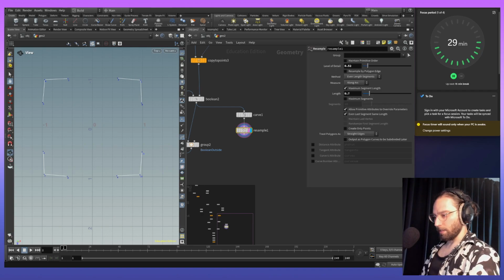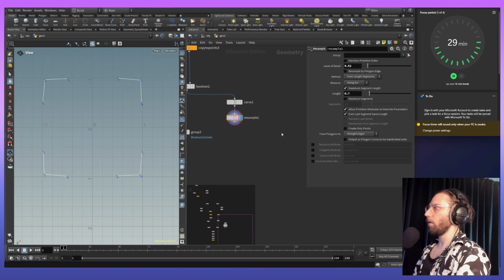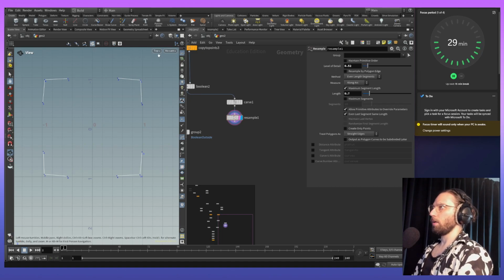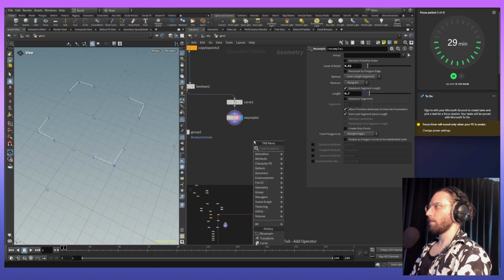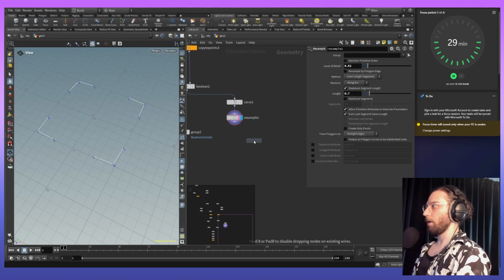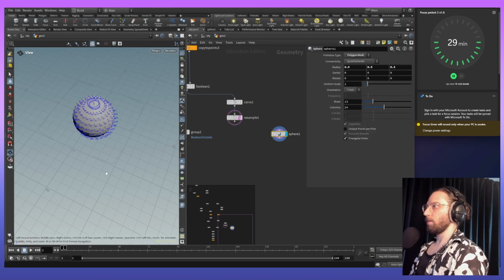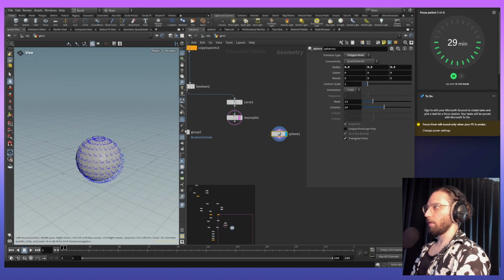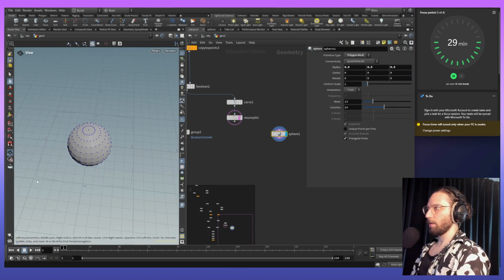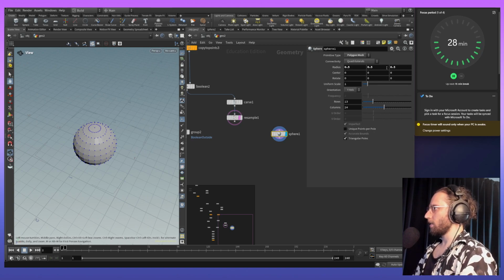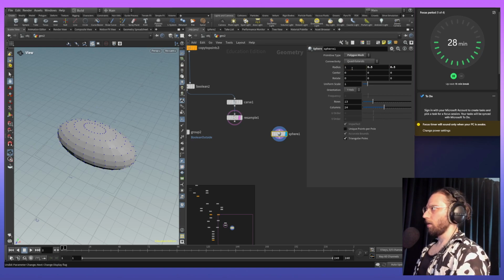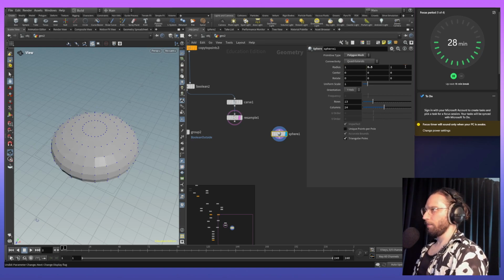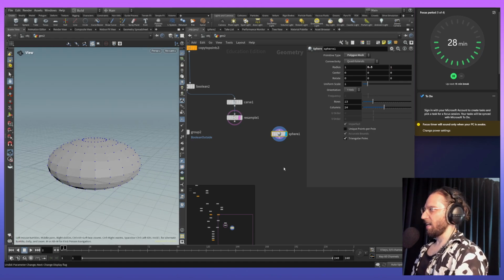Okay, so let's go, guys. So we will add a sphere now. So let me go back to my perspective viewport, and we will add a sphere. All right, so sphere, here we go. So let's view the sphere. We see it has a lot of points. We don't need the point number. We just want to see it. Let's make its radius in 1 point a bit bigger, maybe just wider, basically. Yeah, let's do this, for example. Just like that. And now we will add a clip.